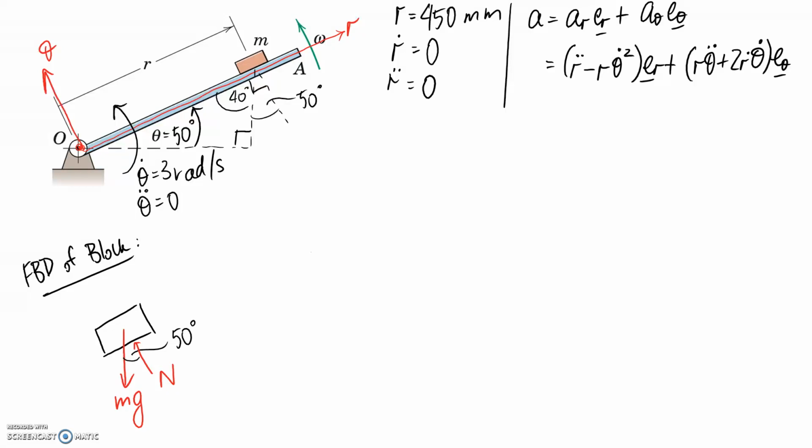Alright, so we have one more force that we need to apply, and this is the friction force, which is the one we're probably most interested in because it's going to help us solve for the coefficient of friction. I'm going to assume that as this rotates around, at our instant, this block is going to try and fall down the ramp. So friction needs to oppose the direction of motion, which means it's going to be directed back up the ramp. So the force of friction is equal to the coefficient multiplied by the normal force, and we're looking at the static situation where movement hasn't quite occurred. So it's going to be this static friction coefficient that goes in there.